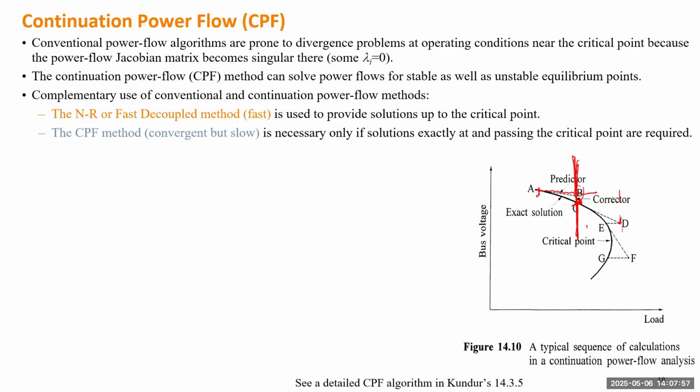Then you have to assume a different load model with constant voltage but arbitrary load. Okay, that is more aggressive than a constant impedance load. So that can guarantee this load characteristic will be able to intersect with the PV curve. So beyond that point, every time you just draw the load characteristic as a horizontal line with constant voltage. That can guarantee an intersection with the PV curve.